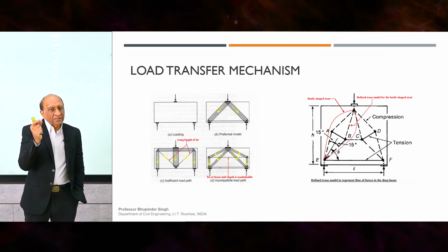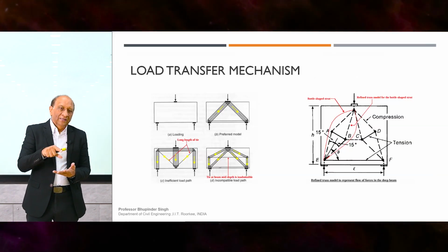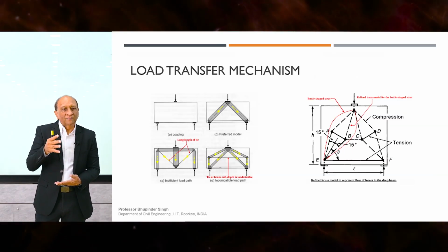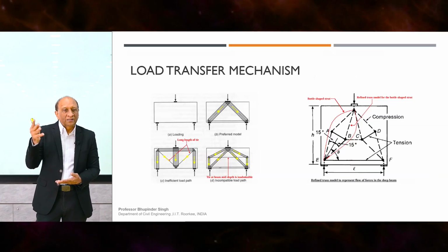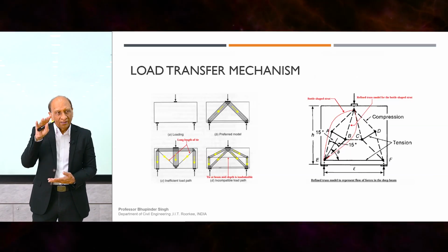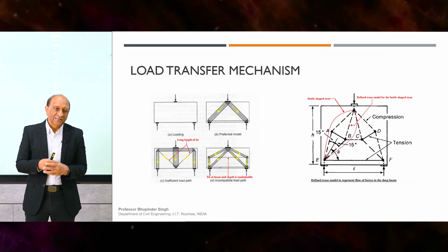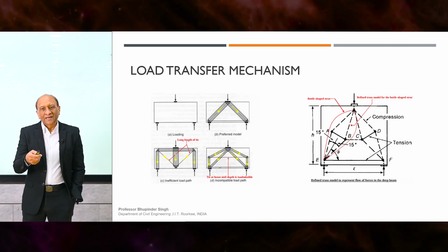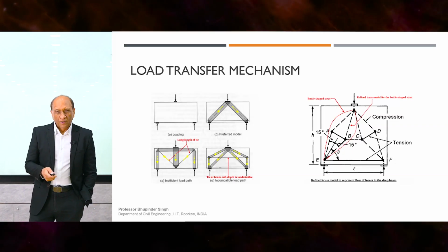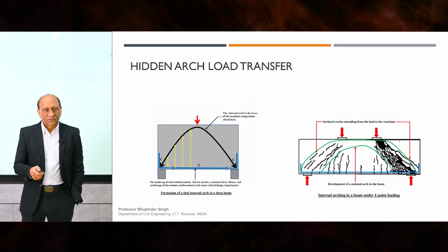And the struts can be subdivided into smaller portions. What we're showing here is that if you increase the reinforcement distribution at the bottom and increase the size of that band, then basically you are trying to make sure that your joint is big enough, you have smaller diameter bars spread around, the cracking will be prevented, and so on. So secondary trussing or minor trusses can also be used. And then the idea that within each strut, there is a sub-strut which should also be prevented from cracking. So this is a typical problem in a deep beam or transfer girder type structures.